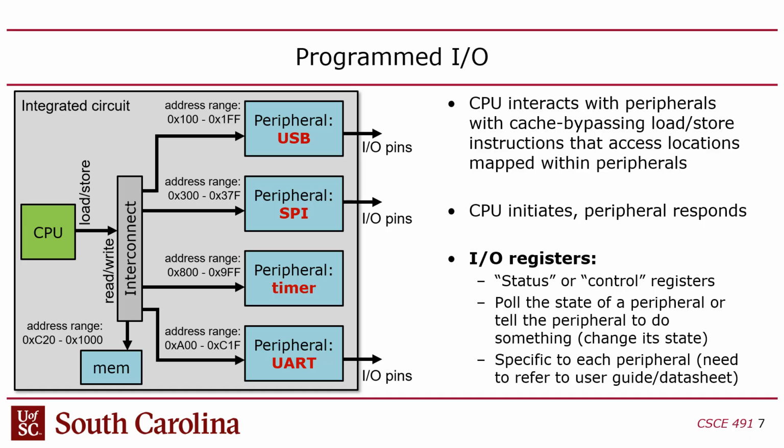programmed I/O. So I already introduced this. Programmed I/O refers to the style used here to have hardware and software talk to one another. The whole idea behind programmed I/O is that the CPU is the master. The CPU is the only entity that can initiate communication between the software and the hardware. And the way it does it is ultimately through either pure load store instructions, like you learned about in 212, or some CPUs have special variants of the load store instruction for I/O.